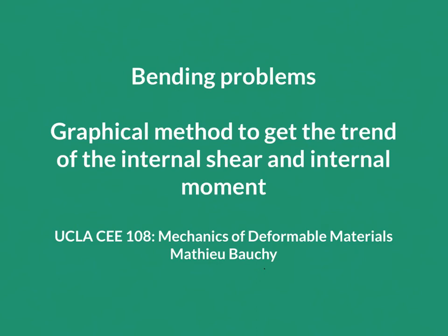So in this video we are going to briefly review some bending problems, and especially we are going to see how to use a graphical method rather than an analytical method to get the trend of how the internal shear and the internal moment is changing as a function of the position.